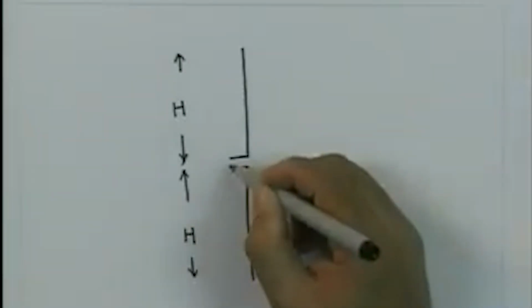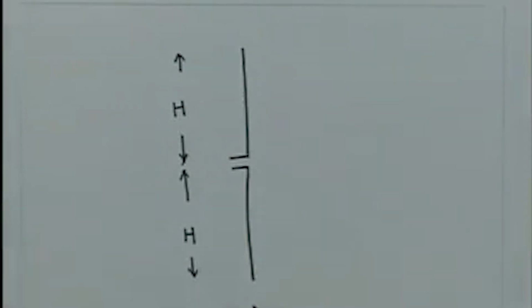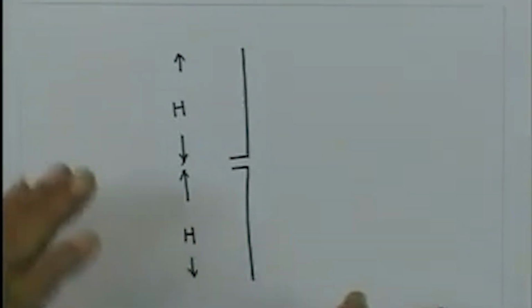Because of the excitation at this point, the current is going to spread out on these wires, and as we have seen, the dipole antenna can be visualized as the extreme case of a flared up transmission line. Without going into much detail of how the current distribution is obtained on the dipole, we will investigate the radiation characteristics assuming that the current distribution on the dipole is known. As I mentioned earlier, the current distribution calculation is a rather complex issue.